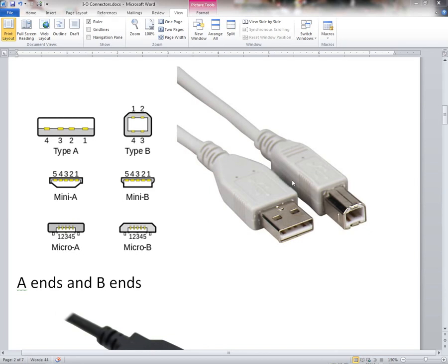USB allows you, each USB root hub, and I'll talk more about this in a second, can handle 127 devices. USB supports daisy chaining. So through the act of daisy chaining hubs, and if I remember correctly, you can only daisy chain up to 5 hubs. The other thing is that USB is bus powered.